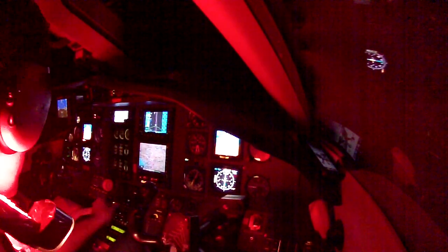You're going to align this to the runway, right? Is it going to align automatically, or are you going to align? No, you have to set the course selector. Whatever the course is, you see over here it says course? You have to set whatever course you have on the ILS. So you have course, you have to set localizer, and you have to put the localizer frequency also.